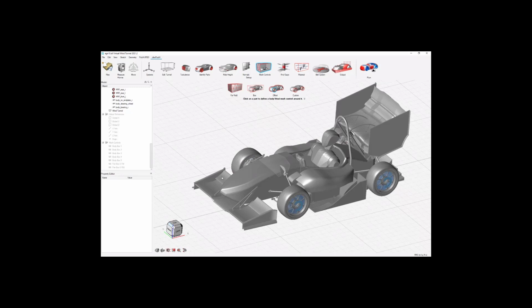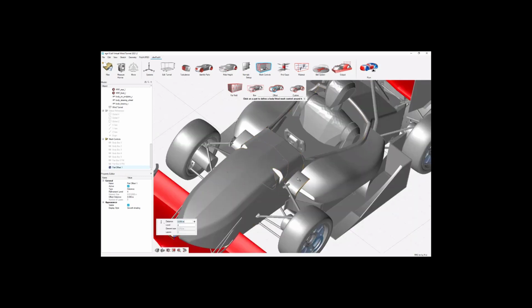So now we can click on parts. First I will select parts that will be included in the finest refinement, which will be refinement level 7. And I will use this one for the flaps and the main plane of the front wing. Oops, sorry, I misclicked, so you can see there are now 2 part offsets. We don't need that, so we can just delete one of them. And then click on the other one. You can see this triangle lights up. So if you double click on that, you can go back to the controls again. And now we can select all the missing parts. And I also want to select those little wings for the finest refinement as well. Okay.